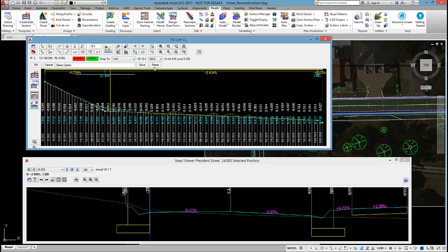So what I want to do on my curb design is project two grades from the road center line, say at -5% and -2%, and show those bands on this profile. And then as I'm designing the curb, I can see straight away that I'm designing suitable crossfall.